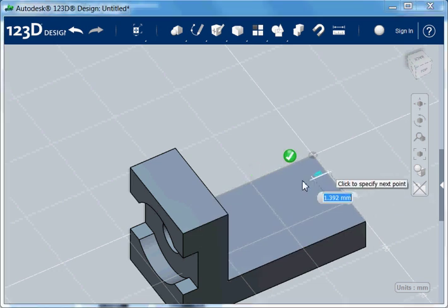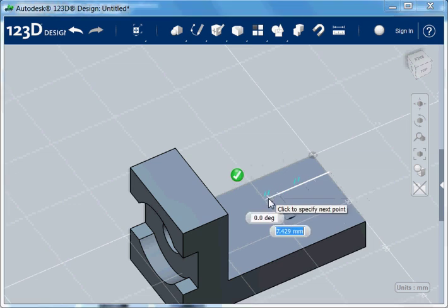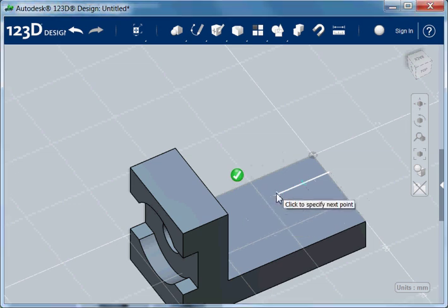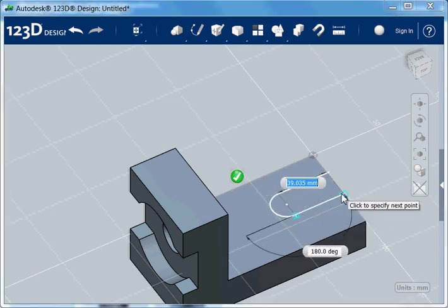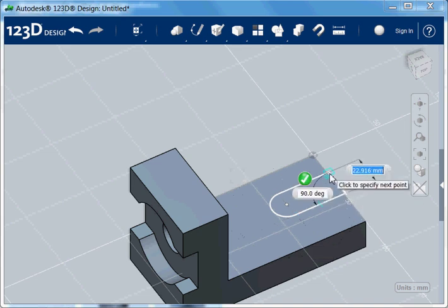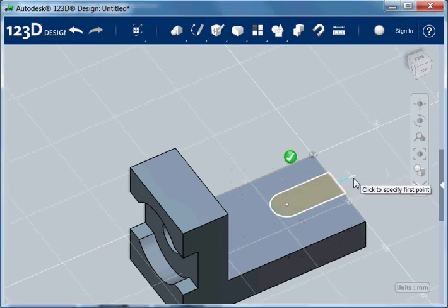And that is if I draw this line, and I wait here on this point, and then with my left mouse button pressed, if I move, it will make a radius. I just put it somewhere. I hover over this point so they are equal, and now it is done.